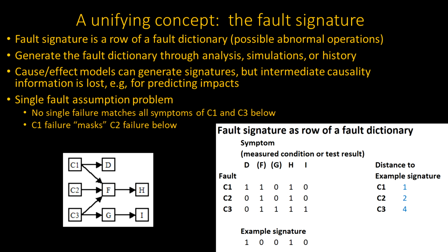So these models can have problems, but the biggest single one is figuring out what to do if there are multiple failures. And as I said before, at any particular instant in time, two simultaneous failures probably won't happen. However, they might have occurred at different times, especially on a long mission. Some sensor might have failed or some fault might have occurred. It may be unfixable and it may go on for years. So you have to allow for the possibility of having them. But nonetheless, it is such a convenient representation that an awful lot of times you are going to be dealing with a fault signature.